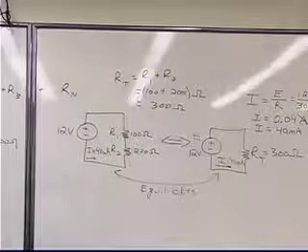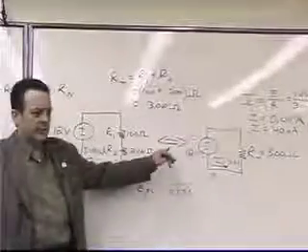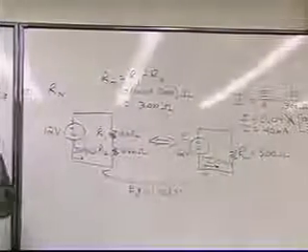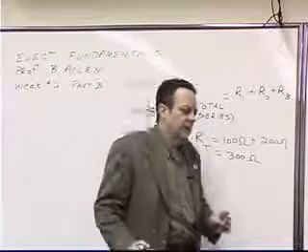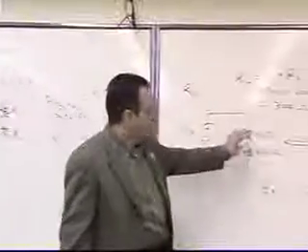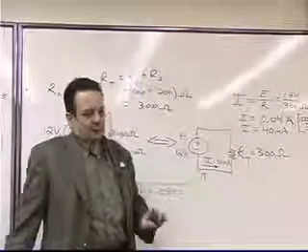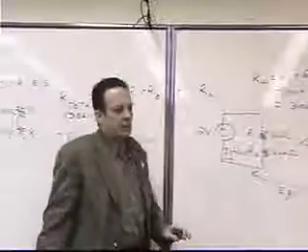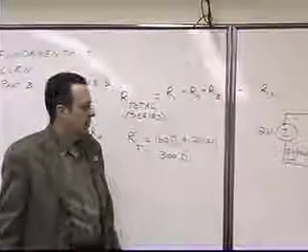Those are equivalent circuits, and that's what this symbol right here designates. They're interchangeable with each other. In other words, they're not physically the same, because this one has 2 resistors and this one has 1, but they are electrically the same, because all of the electrical properties are the same between the two circuits.